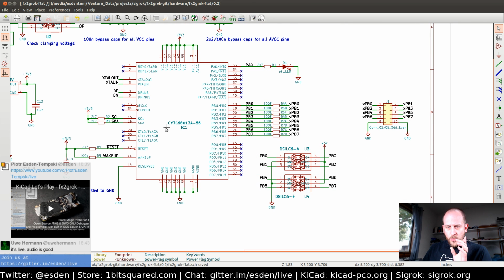Okay, so going back, I think we should add the pull-up resistors because this way we have a defined status of the lines if they are not connected to a target. And they should be high-value resistors to not require a lot of drive from the target to overpower those pull-up resistors. So I think maybe something like 100K should be good enough. But then also you have a defined status so that when the logic analyzer reads the data out, it will not have like a jiggling output because it is in an undefined state.